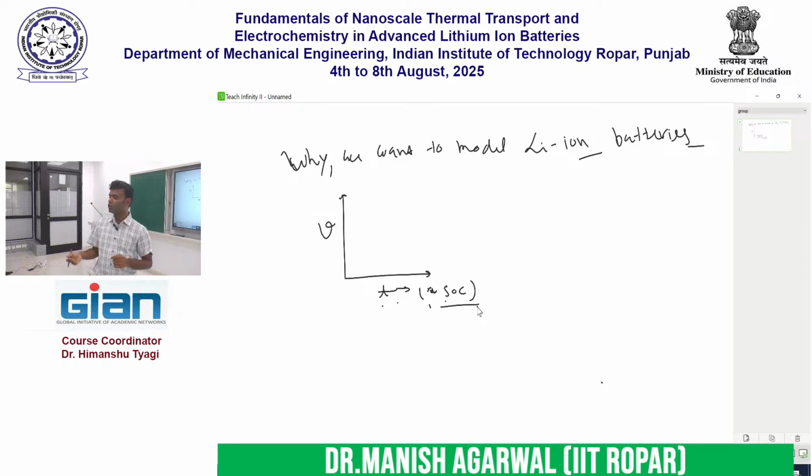So what is the typical voltage of a lithium ion battery? Okay, 4.2, 3.6. These are the typical numbers. But that is when the battery is fully charged. When the battery is 100% charged, the typical voltage is 4.2 volts. But slowly the terminal voltage decays, right? So the typical graph looks like this.